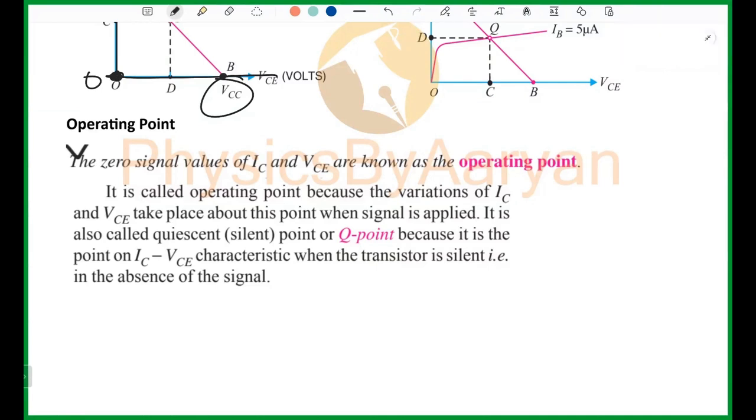I have one question. Yeah, please. You said that this is a reference line and it will not change, but load line depends on the RC, right? And resistance depends on temperature in some sense, right? So if temperature is changing, the load line is also changing.